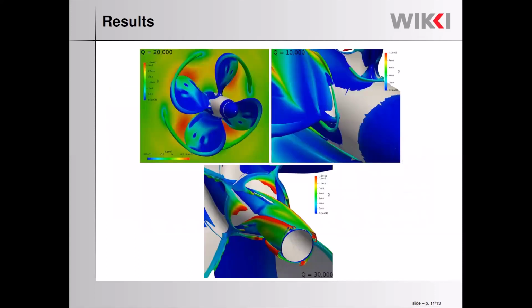Yes, and these regions of very low pressure are basically that. So your tip vortex is just propagating through these regions into your domain in the axial direction. And also some other expected coherent structures. So you're getting these horseshoe-like vortices at the tip of the blade, where the blade meets the hub, and also a couple of interesting structures just where the hub is attaching to the shaft.